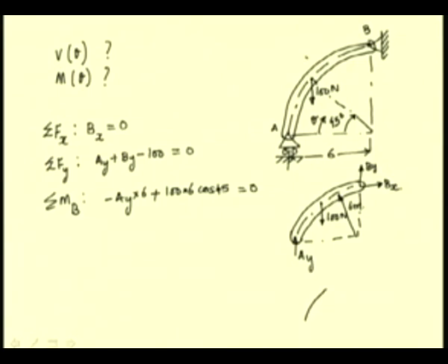Let me call this C and O. So, we are considering a section of this beam before the mid section C. So, at A we have the external reaction, and we have the shear force V transferred to the member, the axial force, say H, and the moment M. So, this V, H and M are the resultant of the internal forces at this section.